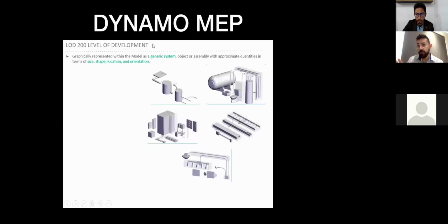When you go to Python script, you can connect to the Revit API, you can connect to other APIs, and you can create nodes that will mix and match things outside Dynamo and Revit. So my best recommendation will be to start by creating nodes, then use the node to code option, and with that start learning how to code by commands in design script.